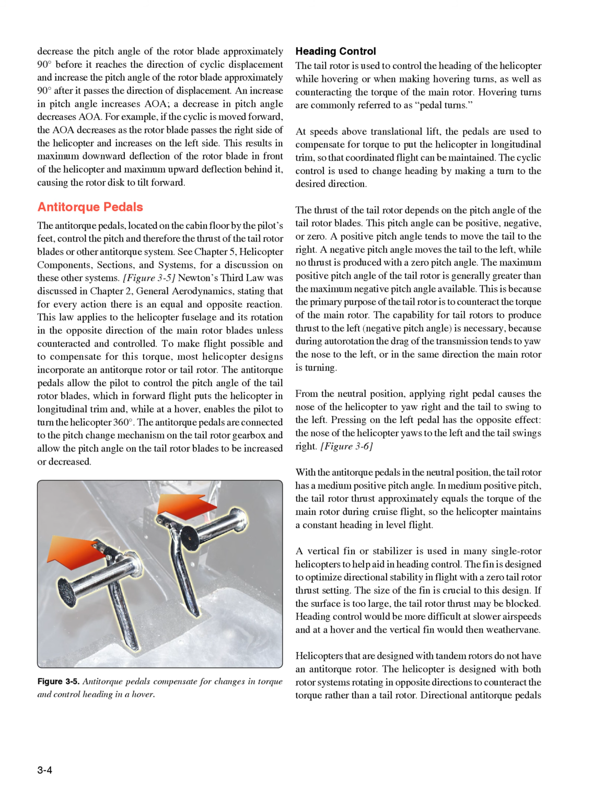The capability for tail rotors to produce thrust to the left, negative pitch angle, is necessary because during autorotation the drag of the transmission tends to yaw the nose to the left, or in the same direction the main rotor is turning. From the neutral position, applying right pedal causes the nose of the helicopter to yaw right and the tail to swing to the left. Pressing on the left pedal has the opposite effect, the nose of the helicopter yaws to the left and the tail swings right.